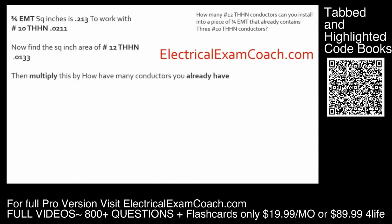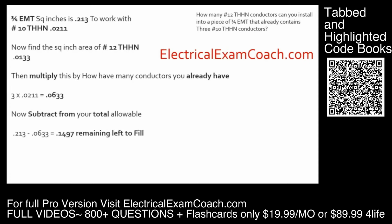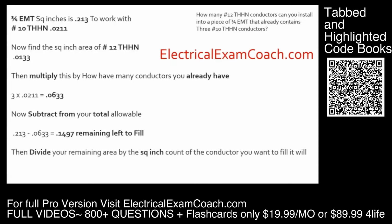We're going to multiply our conductors that we already have. We have 3 number 10s multiplied by the value for a number 10, and that gives us this number. Now to figure out how much space we have left, all we have to do is take our total fill area, which was 0.213, subtract the number 10s, and then that lets us know we have 0.1497 remaining left to fill.